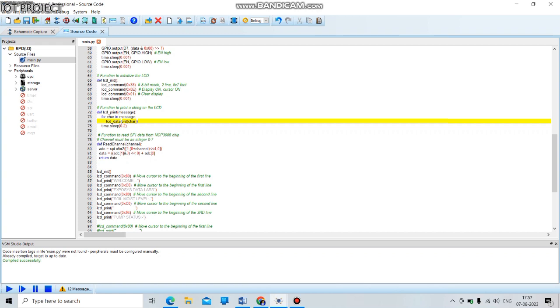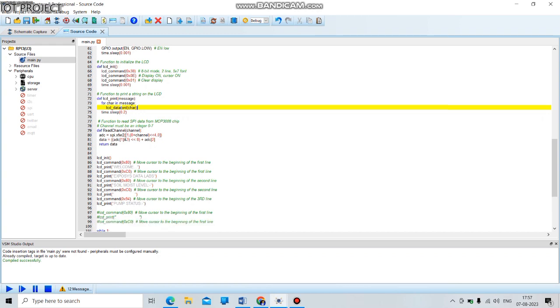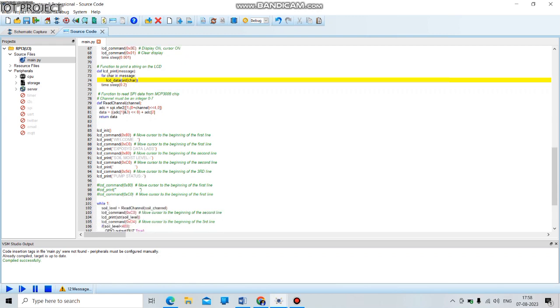The first bit shows the status, that you are ready to take the data. So we have to convert this data into 8-bit data, 8 plus channel, and we have to shift it to the fourth position on the left side. And what does this function return? This function returns 10-bit data, and here we have to convert the 10-bit data into 8-bit data form, because the data variable only takes 8-bit data. So now we return this data.